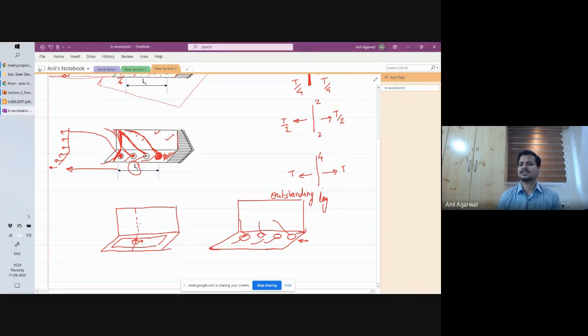So we are introducing less eccentricity. But if we are far away from that edge, like here, where the holes are, then we are transferring very little force to the other leg. So that is also one parameter. Likewise, there are a few geometric parameters. Thickness also plays a role.